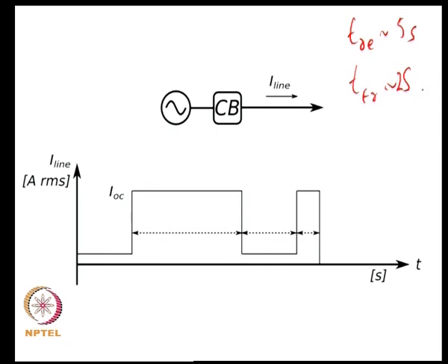But for some reason, say your overcurrent lasted for 1.99 seconds and the overcurrent went away, it means that the breaker nearly tripped, but it did not actually trip. So, it is still staying closed at this point, and over here it is actually having a reset action.